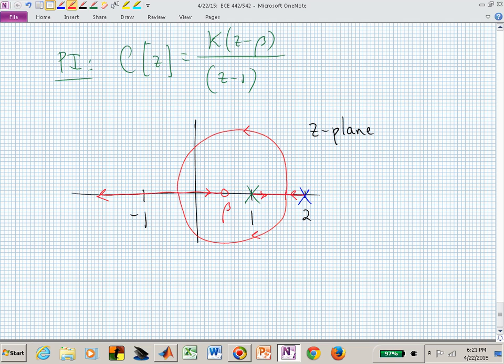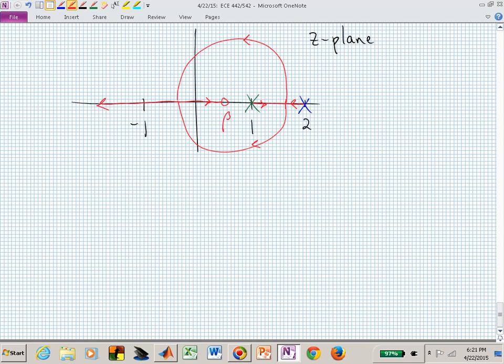I know I can stabilize my system with this structure, this PI control structure, based on this thought process. What if we select beta? Now, this one we just sort of plopped it down. What if we select beta to produce desired root locus paths?